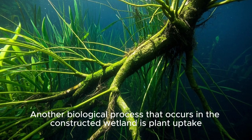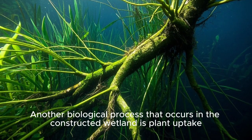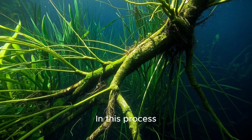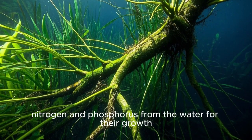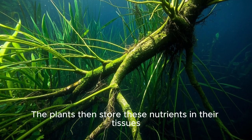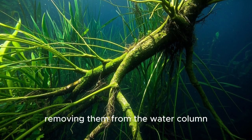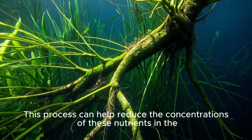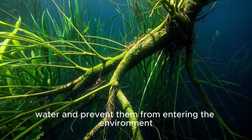Another biological process that occurs in the constructed wetland is plant uptake, also known as phytoextraction. In this process, the aquatic plants in the wetland absorb nitrogen and phosphorus from the water for their growth. The plants then store these nutrients in their tissues, removing them from the water column. This process can help reduce the concentrations of these nutrients in the water and prevent them from entering the environment.